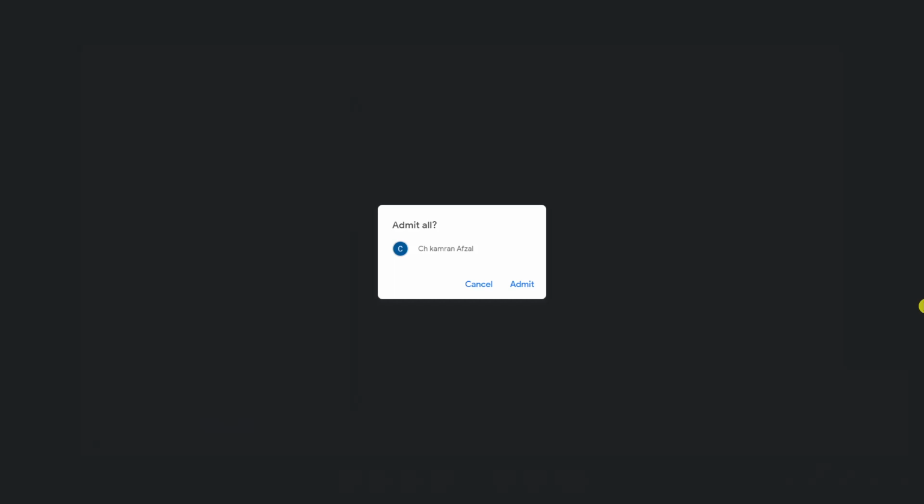So now for this one surface when we are running, we are getting a list of trues and falses, whether they're equal to minus one or not. So you can see all of them are false apart from number four, which is actually minus one. So now we know that number four is the one that we need. We are using a filter by Bool mask to filter out all the surfaces that we obtained in the first step, which is this. So now if we filter, only one of the surfaces will come as true.